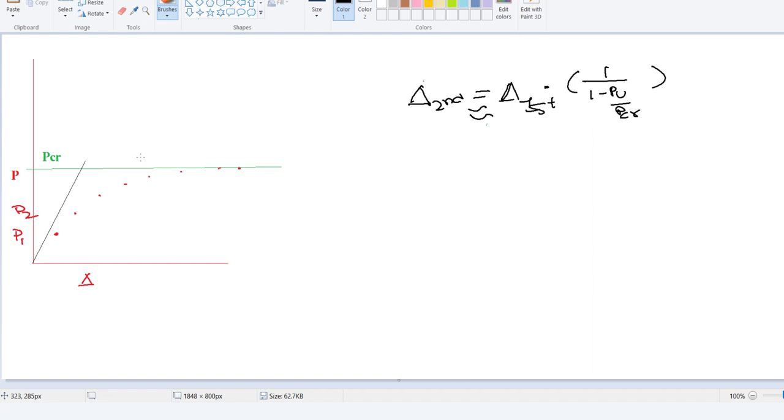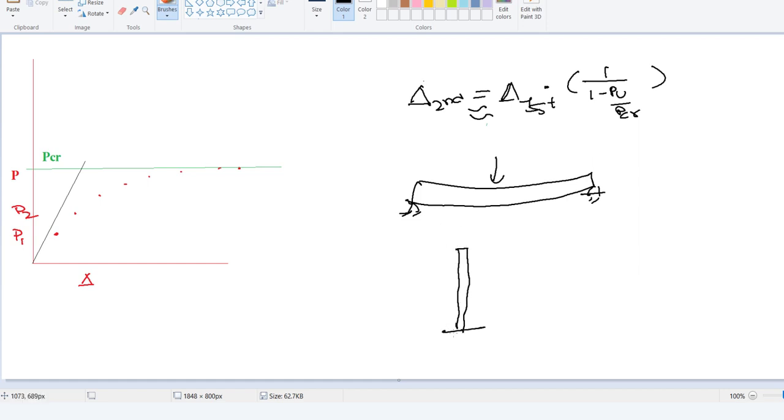And it's not necessary that bending would happen only along the direction of the load. If I say this is a simply supported beam, that means it's not necessary that the bending would only apply along the direction of this load. Bending can also happen if we apply a load P at a certain eccentric distance. Then also we have seen that the bending is exhibited. So this is how we can derive the buckling point from the second order analysis of P-delta analysis.